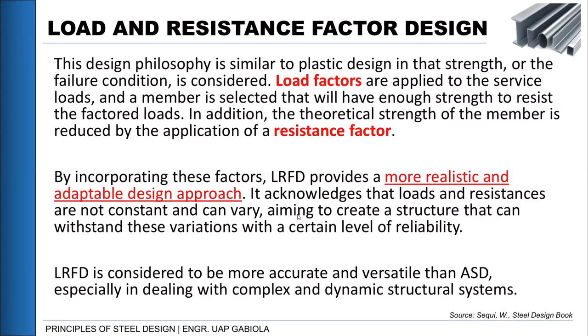So, this philosophy is similar to plastic design in that strength or the failure condition is also considered. So, by the name itself, load and resistance factor. It means the load side, on the left side of the equation that we have on the ASD side, we now consider putting a factor on it, which is called the load factor, applied to our service loads. Okay? And the member will have enough strength to resist our factored loads. In addition to multiplying the left side of the equation, we are also introducing a resistance factor, similar to the function of the factor of safety.